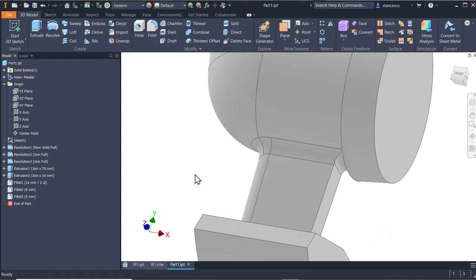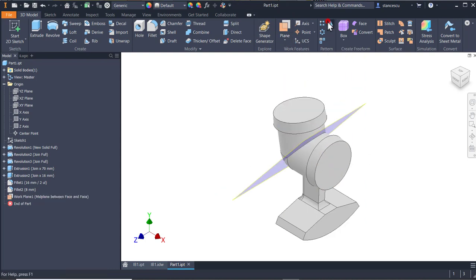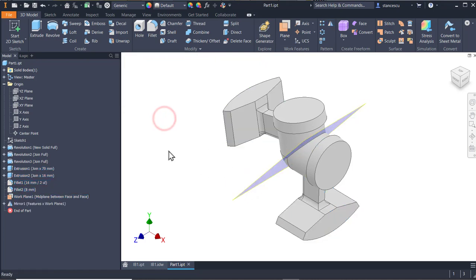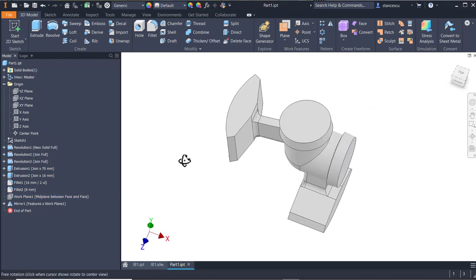Okay. Now I'll mirror this to have the other volume finished. Here, in order to create a hollow inside this, I create the symmetry plane as the mid plane between this one and this one. Mirror of extrusions and 2 fillets about this plane. Okay, we'll use the plane, it is here, but now we don't want to see it.